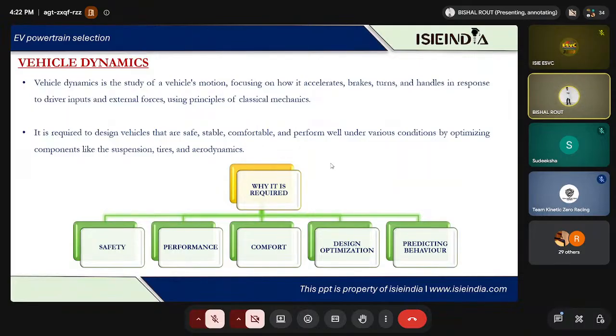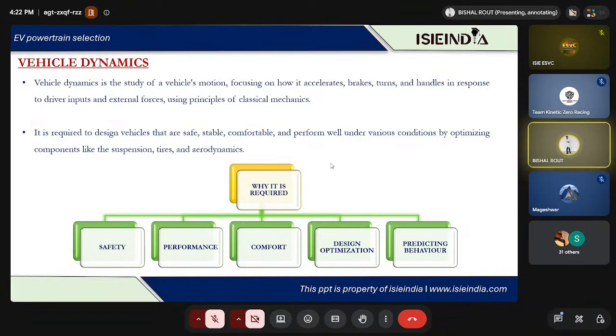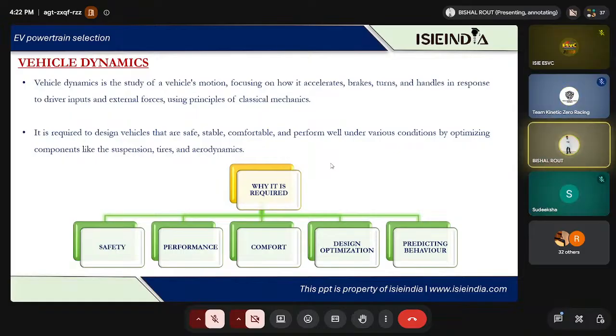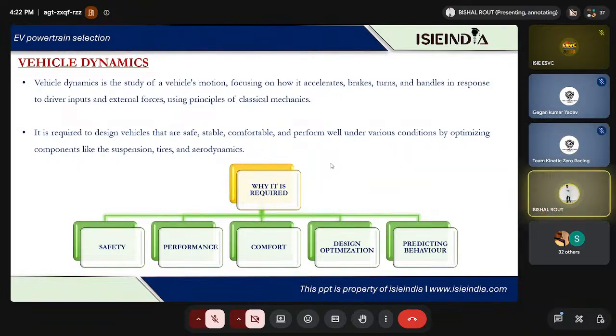What is longitudinal? Vehicle dynamics is divided into 3 parts, which I will explain. The vehicle experiences a large longitudinal deceleration. At the same time, braking causes weight transfer, making the vehicle pitch forward. Front axle load increases, rear axle load decreases, and if the rear becomes light, the tires can approach the available grip limit. That is why vehicle center of gravity, wheelbase, mass distribution, brake force distribution, tire characteristics, suspension, and ABS all matter. A vehicle dynamics engineer can simulate this before testing is done.